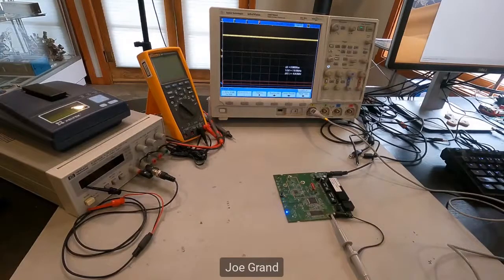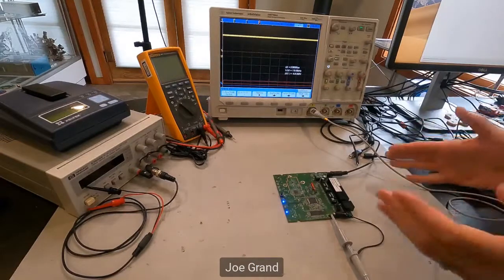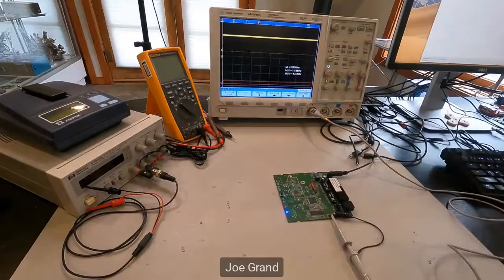But generally, UART is used a lot for this human connection to a board. We'll see boot log information like we'll demonstrate. We'll see access to bootloaders. Sometimes we get dropped straight into a root shell on devices. So even with something very simple like a UART interface, we can compromise boards if they're not designed properly.